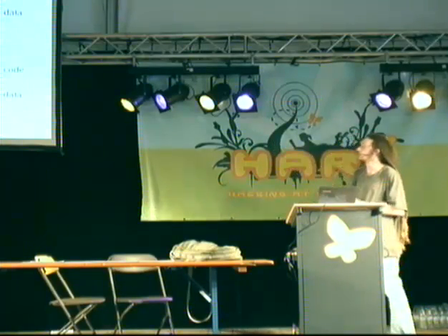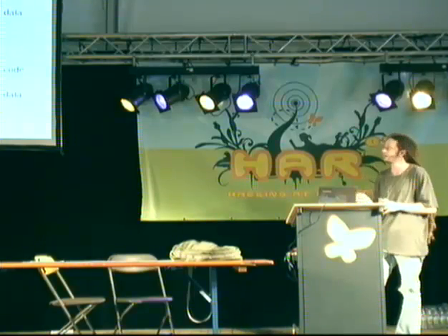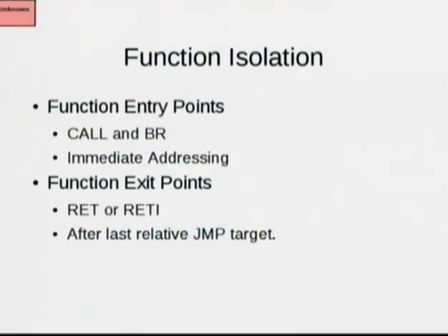This is a more complicated image, one taken out of a physical device. This is a JTAG debugger that Texas Instruments sells for debugging their chips. You can see here in red is the main application code. Up here you have data tables, which are loaded in for identifying target chips. And then at the very top, this red code here is actually a bootloader that proxies interrupts to lower code. And because it proxies interrupts, the password will be the same on all versions. And you can actually separate these two applications.